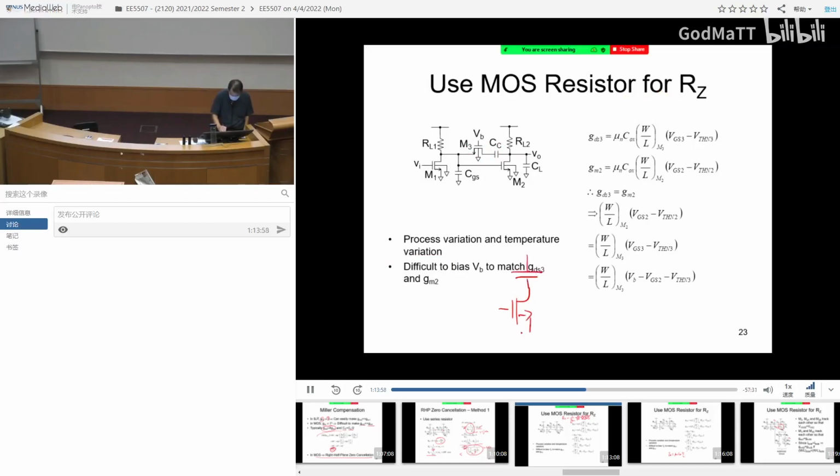Let's say I have the capacitor. Let's say I turn on this guy, VDD. I can conclude this transistor is always in the linear region. If you don't trust me, let's assume you say, oh, this guy always has to operate in the saturation region. If that is the case, the current is going to be half mu n COX W over L VGS minus VTH squared. Agree?